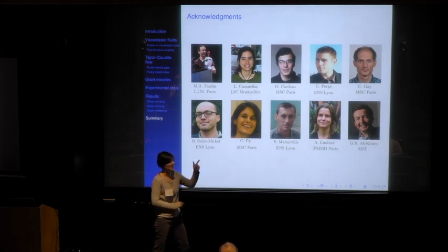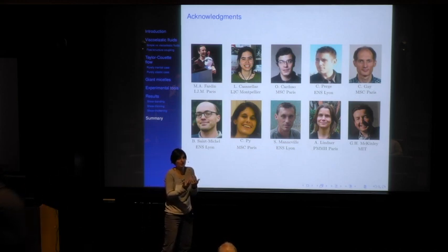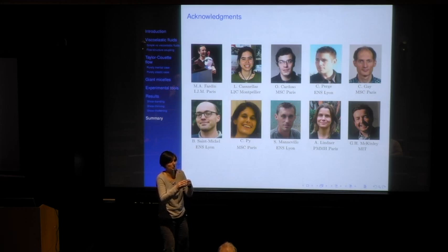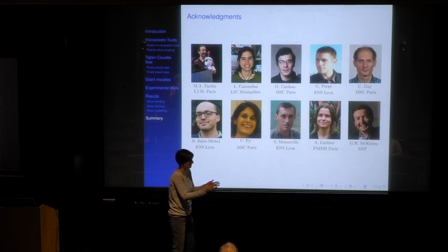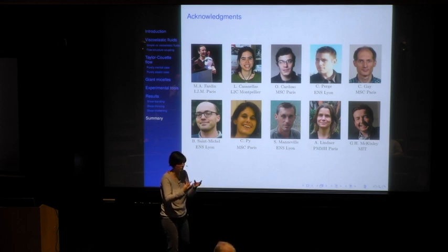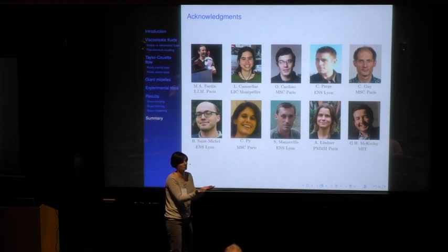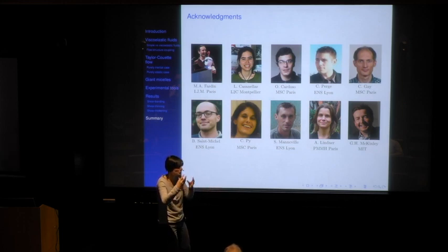But in our case, in the dilute case, you have nothing. To have something, you have to trigger the transition towards the entangled state, so we take advantage of this transition. We start with something dilute with no interaction, and there is a change of the mesostructure of the system, which starts to entangle. In that case, you can build up elastic stresses. So we will never observe in this kind of system the same transition as has been observed in polymers in the purely dilute case, because we need a change of morphology, a change in the network, to generate elasticity and then to trigger the instability.